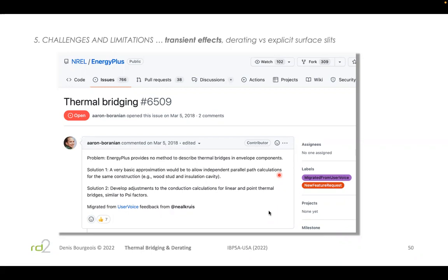So maybe I'll just summarize in other words what TBD does. If you have a default construction that applies to all roof surfaces, but some of the roof surfaces have HVAC components that are resting on supports, and you may have a roof curb, and the area is much smaller, TBD will actually make clone copies of each of those constructions and make them surface specific.